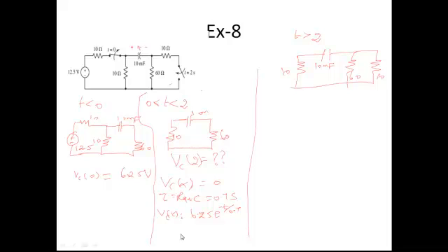Okay. So now what is the question? The question is you need to find out what is Vc of 2. So apply t equal to 2 in this equation. You will get Vc of 2 equal to, substitute 2 here, so e power minus 2 by 0.7. You will get the answer 0.359 volts. Okay, so this 0.359 volts will act as the initial condition for this particular network. Do you understand? So now you have the answer for Vc of 2, which will act as an initial condition